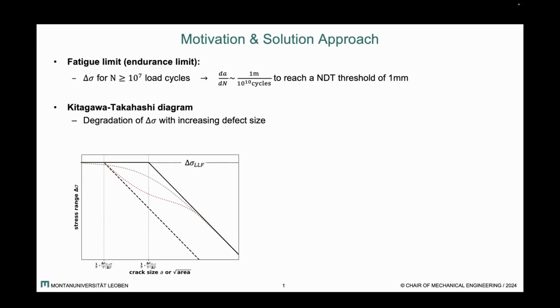So the fatigue limit I will define as the stress range that a specimen endures for 10 million load cycles. The Kitagawa-Takahashi diagram shows us the degradation of the fatigue limit with the presence of defects of a certain size.